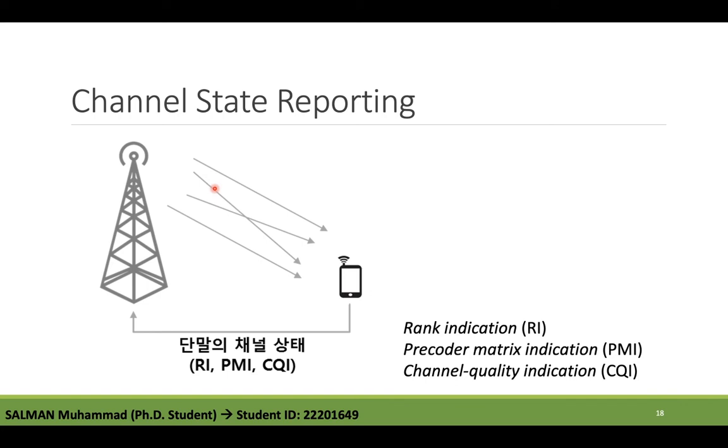Channel quality indicator, which we also call the CQI. The reason to use the CQI as the feedback quantity, instead of, for example, the signal to noise ratio, is that it accounts for different receiver implementations in the terminal. It represents the highest MCS that, if used, would mean the PDSCH transmission is received with a block error rate of at most 10%. So a terminal delivering a block error probability of more than 10% when using the MCS indicated by the CQI would fail the test.